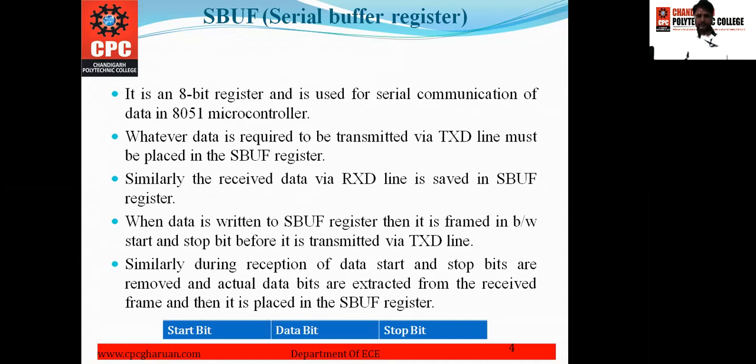The data bits are placed in between both of these start and stop bits. This is the function of the SBUF register: before transmission, the data has to be stored in the serial buffer register, the SBUF register, so that start and stop bits can be removed and the actual data that is needed can be extracted from the transmitted data.